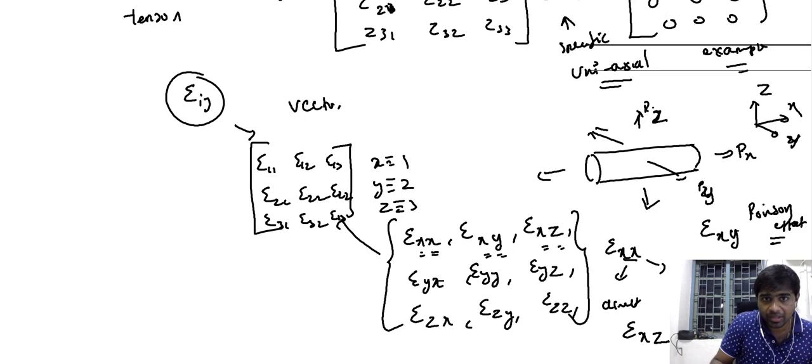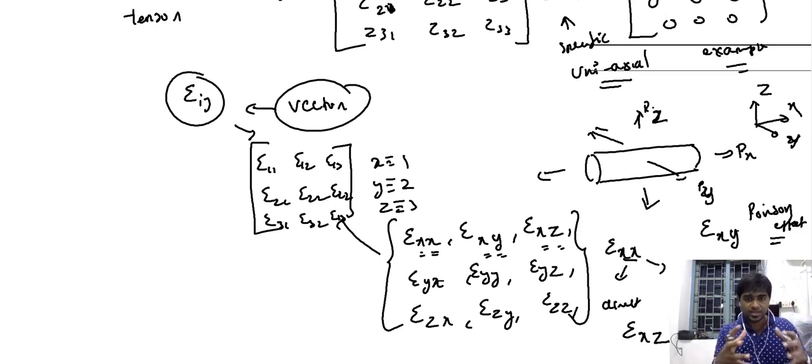Of course, when we simplify the loading condition to a uniaxial loading condition, several entities in this representation will assume a value of 0, and only a few non-trivial entities will be present. Nevertheless, the generalized representation would require treating the strain as a tensor.